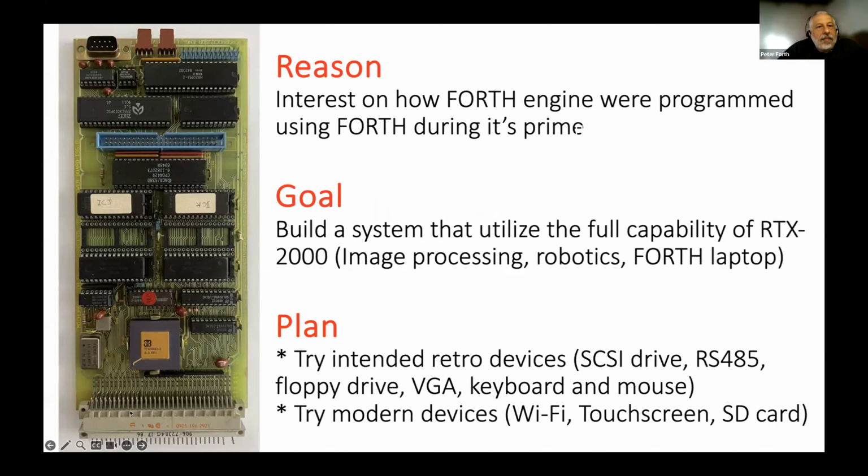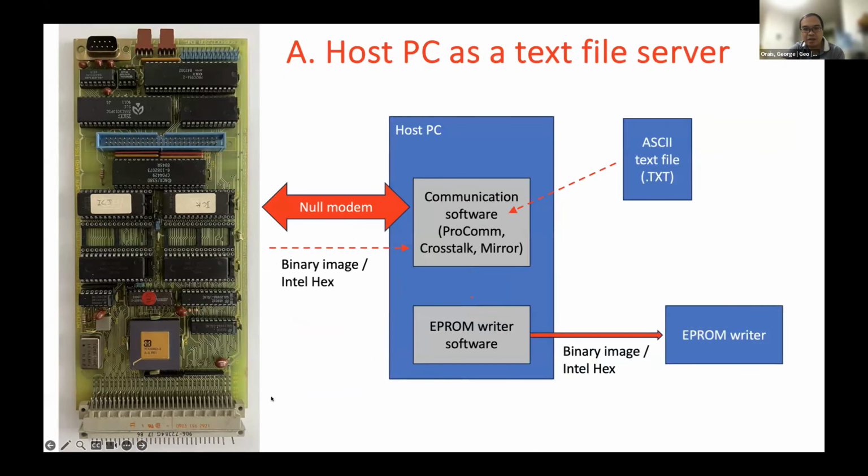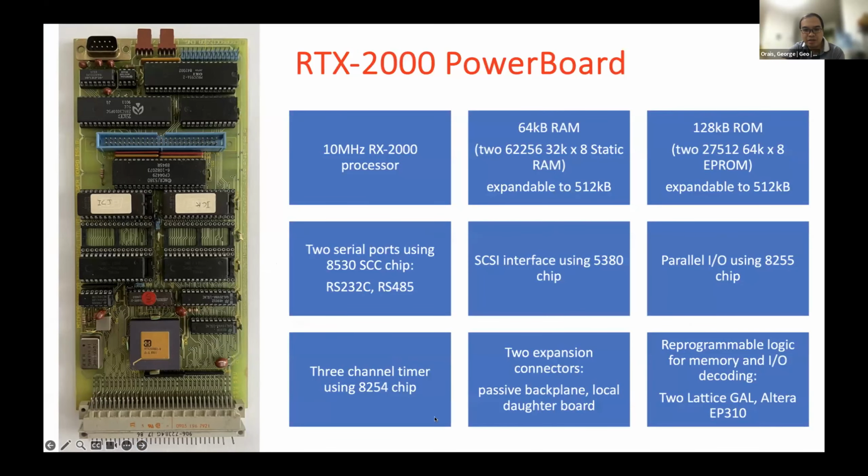Yes, it's a DIN 41612, 96 pin connector. 96, excellent. It's for expansion, the expansion bus. Expansion, yes. And this has the pins for memory address and memory data, and the ASIC address and ASIC data bus.